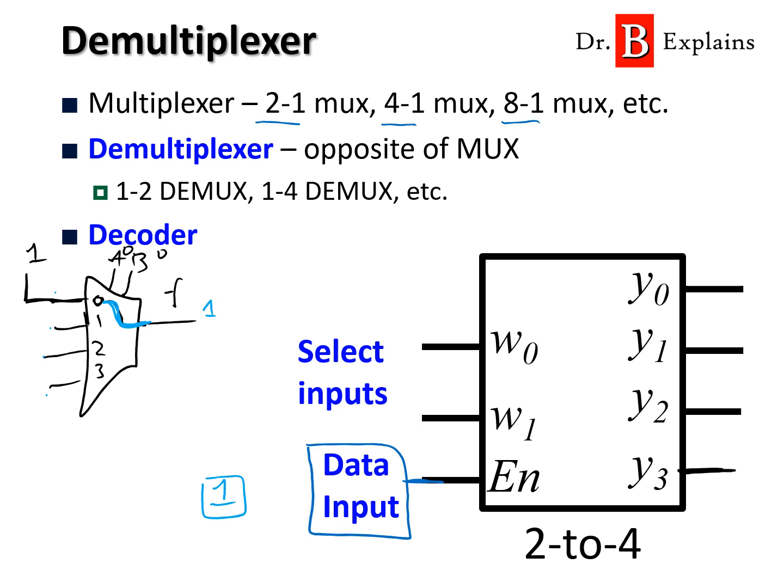If I have my A and B here, I can say, just pass it to the 0, 0, and that value will be sent to here. And if I have a 0 as my data, it would still pass it to here, but now I have a 0. So it's kind of like taking the serial input. I either turn it on or off, and it's going to pass it to this signal or to this other one or to this other one. That's basically what the demultiplexer is.